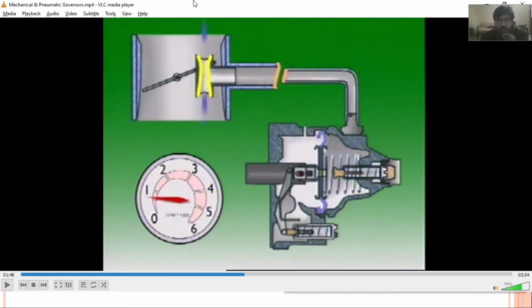And when you press the accelerator pedal, this butterfly valve will be opened, and more air will go through the main Venturi instead of this auxiliary Venturi. So the vacuum inside this diaphragm unit would no longer be there, and the spring will bring back the diaphragm into its original position, and the control rack into the desired position as well. A throttle butterfly controls airflow through the Venturi and into the engine.